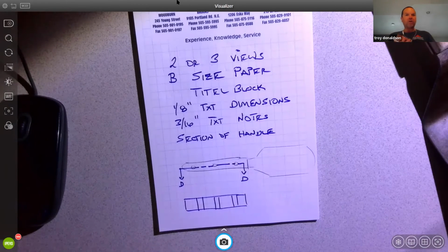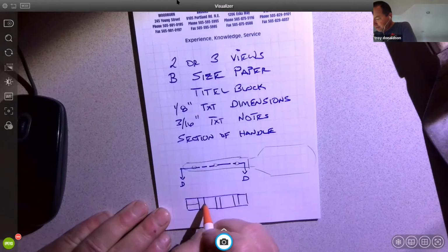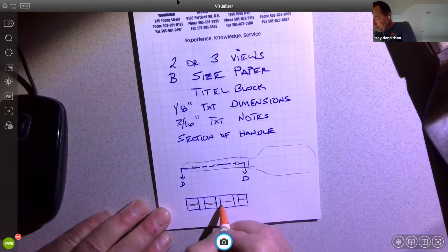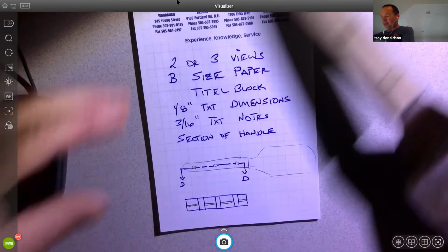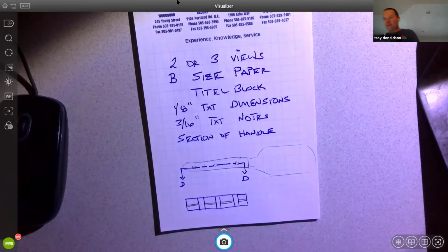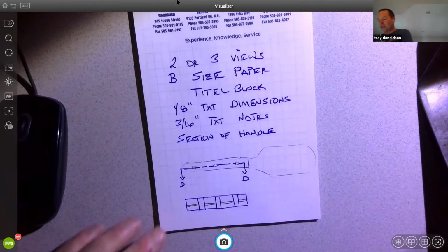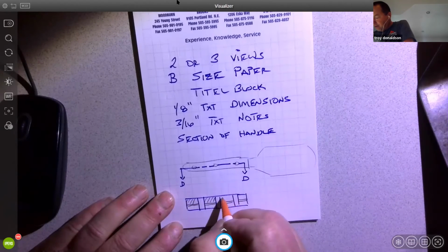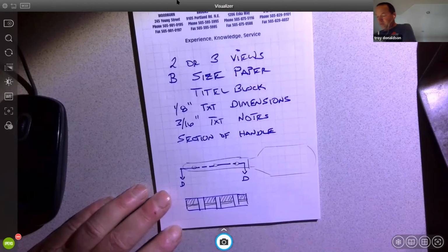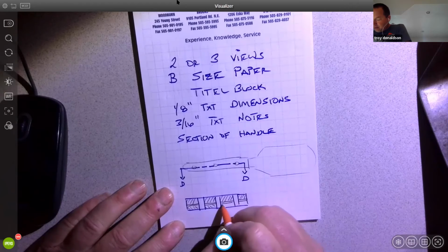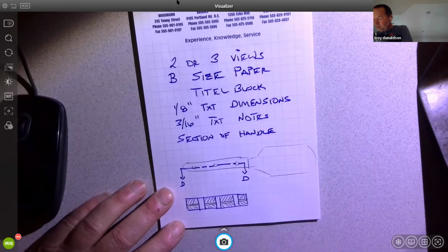But for different materials like wood, and I think there's a center here too, because it's got this metal in the middle, right? So it would look something like that, I'm guessing. We'd show this metal and we'd see these plugs. So this is a pretty good one, right? It's kind of a good section to draw. Each material then would get its own angle. And I would do each part differently. So I might do that one this way, this one this way, showing that those are separate parts.